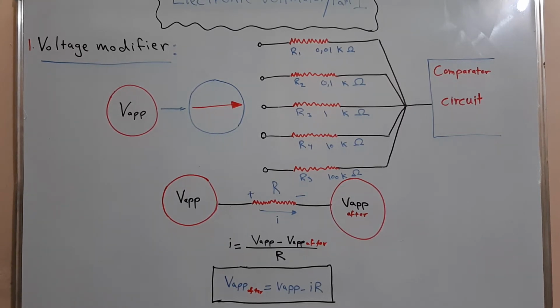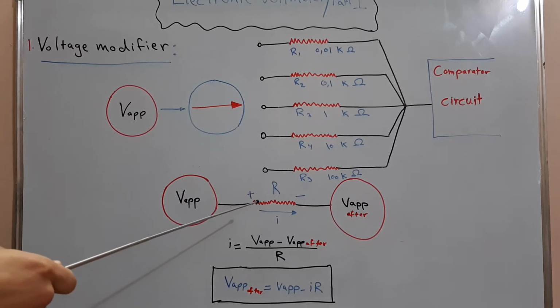Let's suppose that we apply the unknown potential at this point. Then, by the use of the selector disc and selection of a proper branch, a current will rise in that branch, and that branch contains a resistor. Its value is R ohms.